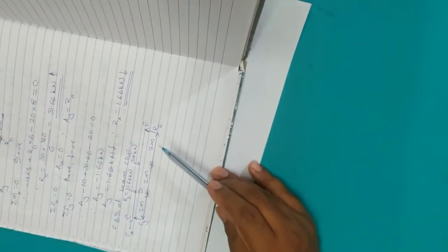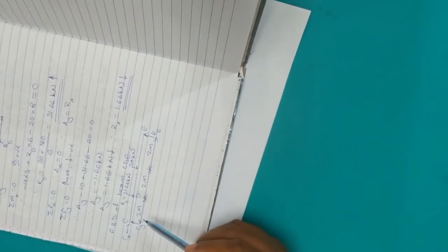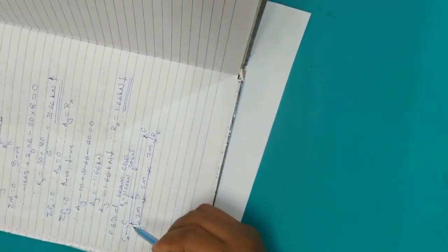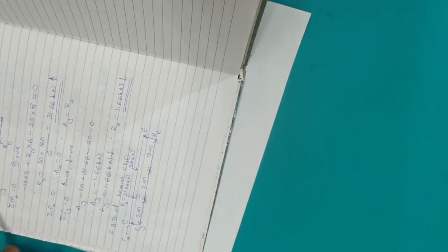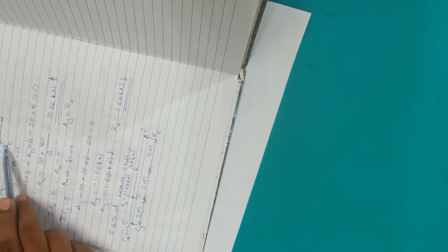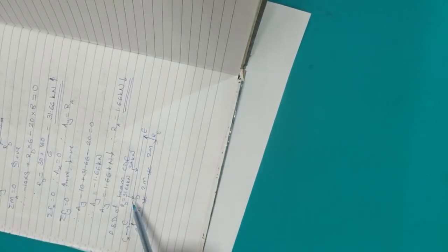So this is how the structure of the beam appears. We have considered the lower portion CDE, and whatever roller reaction RD was there for the beam ADB as a support, the same reaction now acting as a load on the lower part of the beam CDE, and we have taken the same magnitude, but we have changed the direction, right?